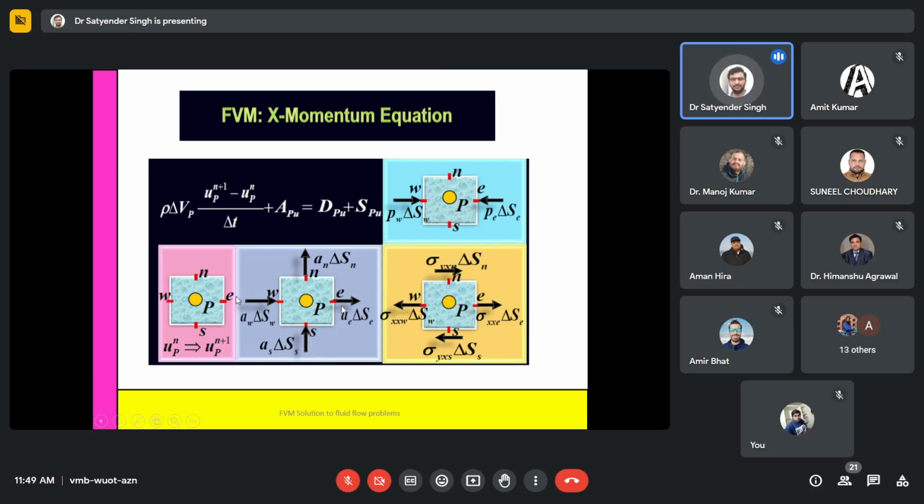As we do an energy balance, say energy entering a system and leaving a system, what it does is let change inside the system. The same theory has been adopted here to make the finite volume method very easy to understand, although in many books the integral form represents it in a very difficult way. So these red triangles and rectangles actually represent the fluxes, wall fluxes. It can be anything like momentum flux, pressure flux, or force, I can say directly.